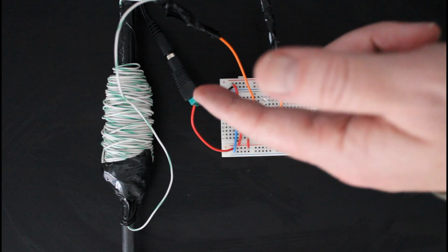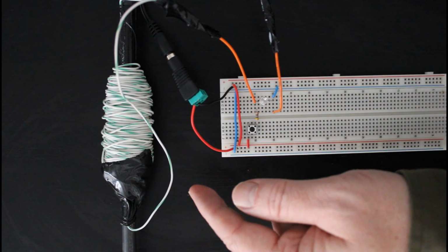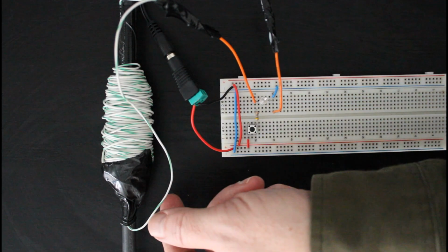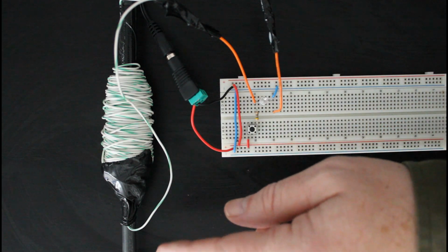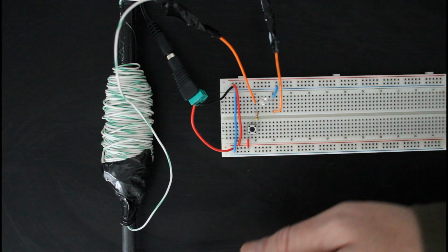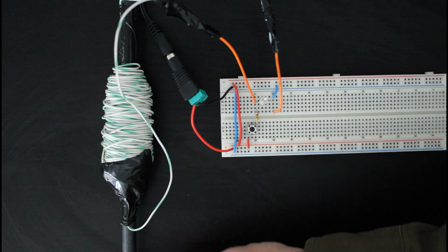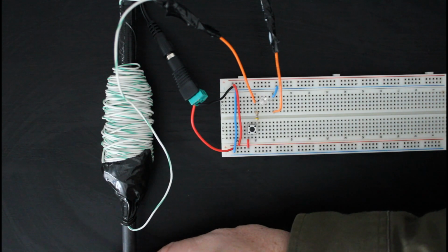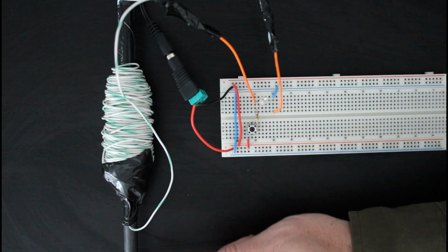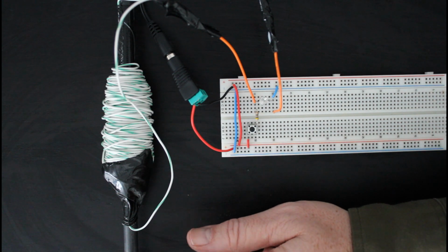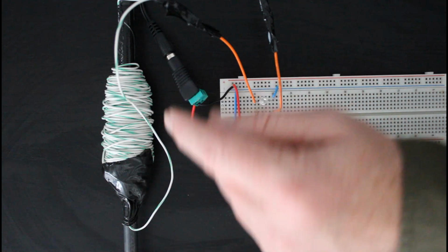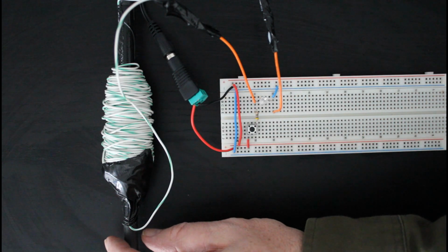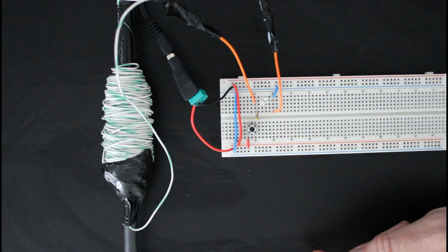So for this experiment, I have yet another coil. And you'll see this, for this coil, I'm back to using ordinary hookup wire, but it's wound tightly around a metal bar. In this case, I'm just using a rod of mild steel. Mild steel is very good for this purpose because it has a high iron content, which means it has excellent ferromagnetic properties, which is exactly what we want when we're using it as the core for an inductor.